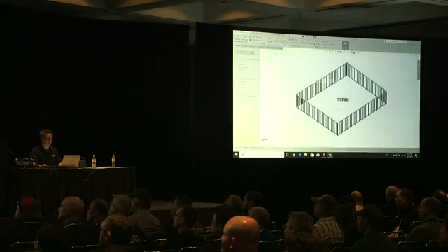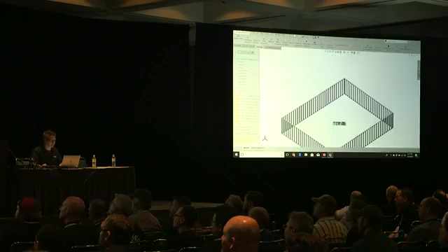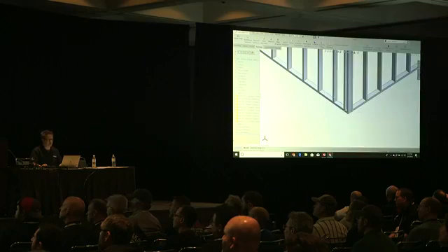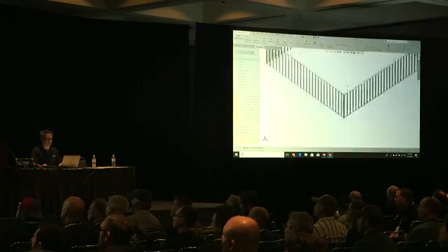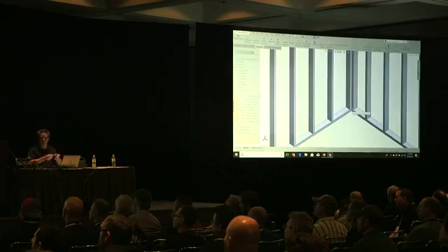Say no. Let's see if either of these has close parts. These are closer than 16. I want to have this one here because when they're hanging drywall, they're going to want that extra piece there. So you're going to have an extra one. So I set this up for that stagger.